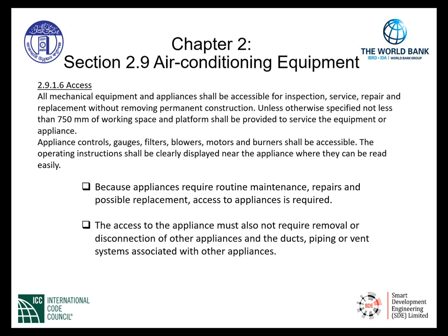The intent of this particular section of the code is telling the code user that we cannot provide any permanent appliances or equipment in the area of the appliance requiring service. We need a clear space, approachable, and large enough for the service personnel to work on and maintain, repair, or replace the permanent appliance.